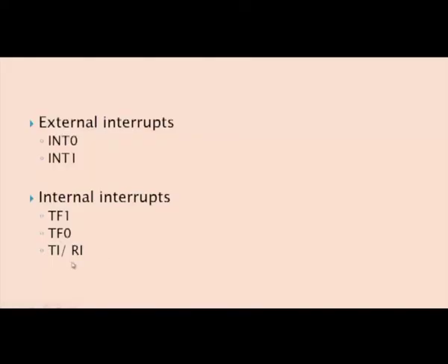These two interrupts are activated by using SBUF. SBUF is one of the special function registers, the serial buffer. When the serial buffer is full, it means it has received data. During receiving, it is filled with data, and after filling, it interrupts the processor to read the data. Once the controller reads it from the buffer, the buffer becomes empty. Empty means it is ready to receive the next byte. That is why it interrupts the controller to take over the data, otherwise the data would overlap.